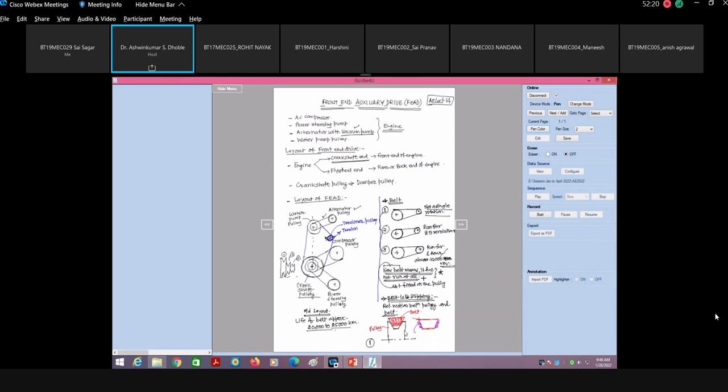if it is shining, that means it is polished. If you observe that the side wall of the belt is polished or it is shining, you can 100% say that the belt is having slip. This is the standard observation one should make.